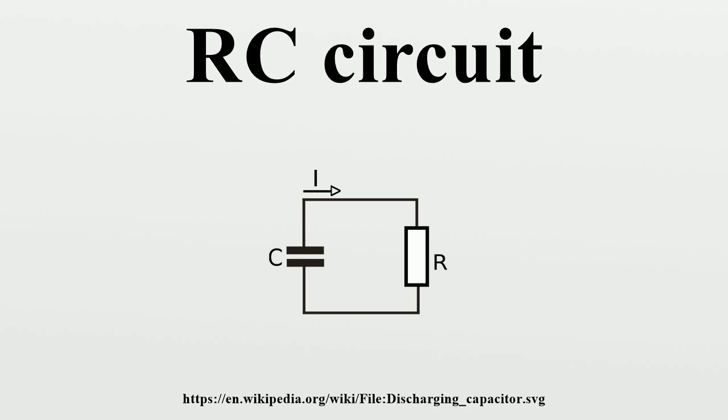Parallel circuit. The parallel RC circuit is generally of less interest than the series circuit. This is largely because the output voltage is equal to the input voltage. As a result, this circuit does not act as a filter on the input signal unless fed by a current source. With complex impedances, this shows that the capacitor current is 90 degrees out of phase with the resistor current. Alternatively, the governing differential equations may be used, and, when fed by a current source, the transfer function of a parallel RC circuit is